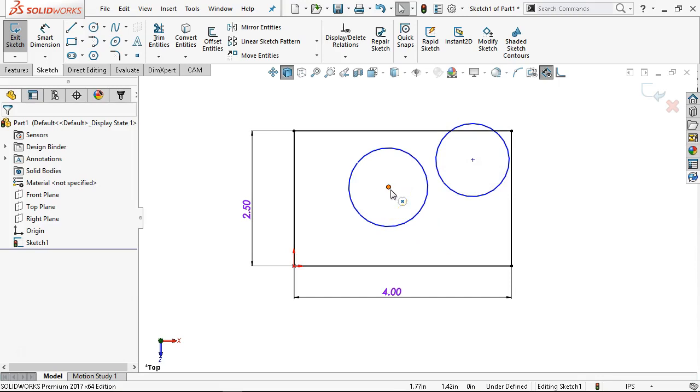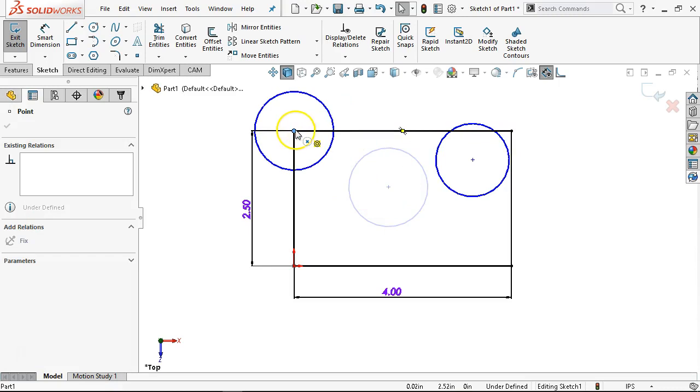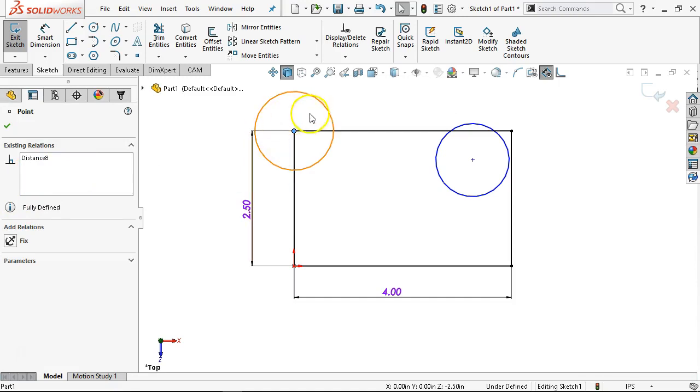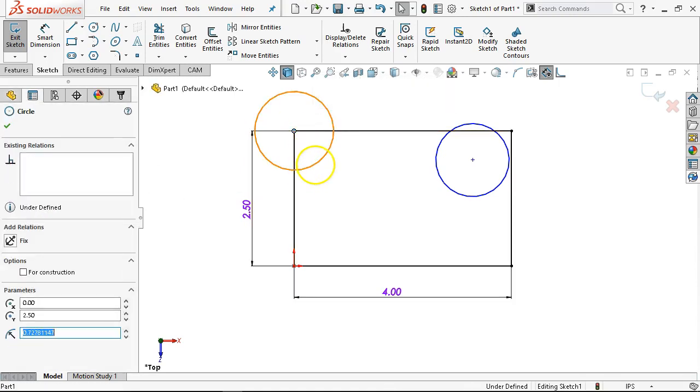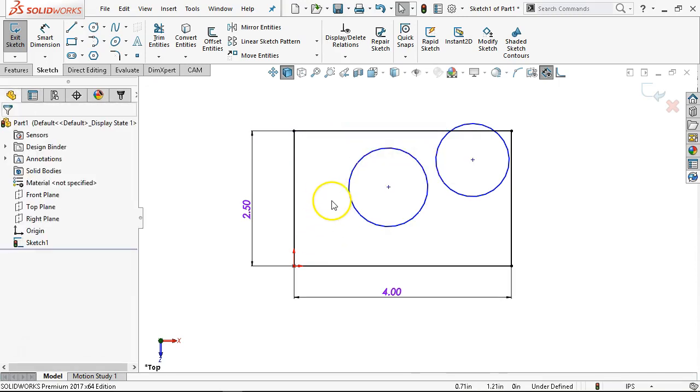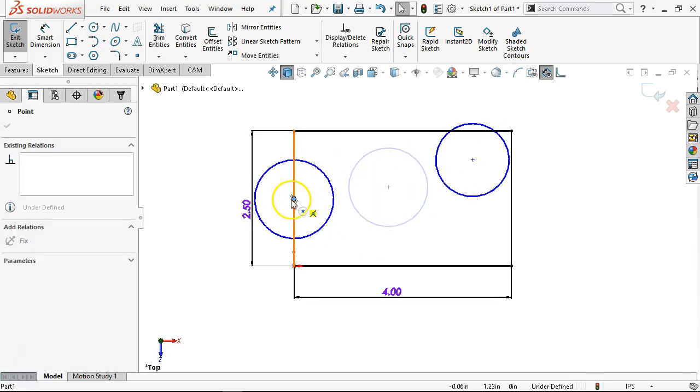So if I want to relate the position, I'm going to select the center point, and then it can go coincident. I now have, well, I got the distance. Maybe it's on that one. Nope. So it might have merged that one too, I'm not sure. So let's go midpoint. All right, so I know I got a midpoint there. So that relation shows up because I inferred. I went to the yellow midpoint box. I dropped it on the center point of the circle onto the yellow midpoint box. That infers the new relation.